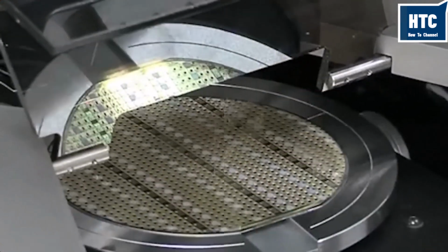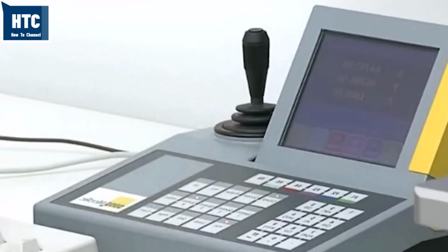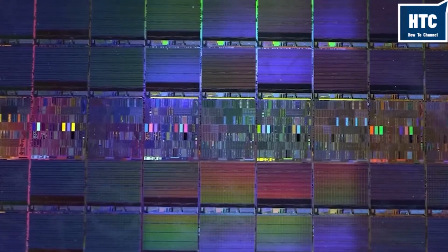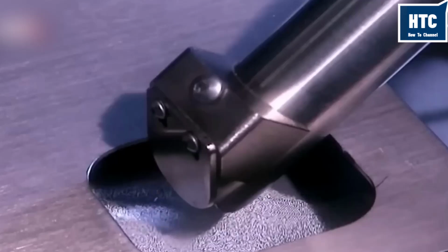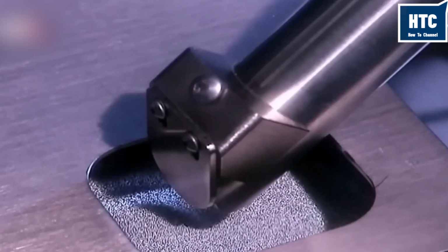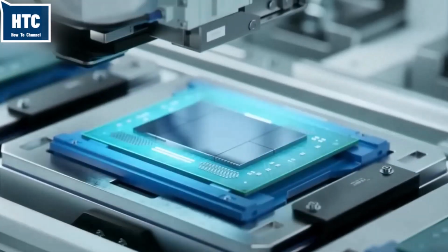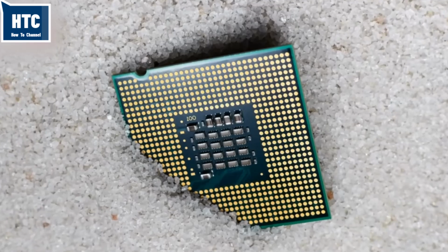The finished CPUs go through binning. Because the manufacturing process is so precise, slight variations in the silicon crystal can make some chips perform better than others. A chip that remains stable at high voltages and high frequencies might be sold as a flagship Core i9 or Ryzen 9. A chip from the exact same wafer that has a few defective cores might have those cores disabled and be sold as a Core i5. This maximizes yield, ensuring no working silicon goes to waste.